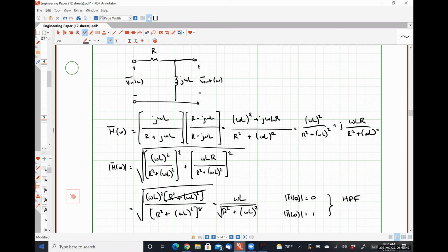But then you also get into problems called the skin effect and all that kind of good stuff, where you have to be careful about the size of the conductors that you use, because at very high frequencies... so in a DC circuit, all of the current that passes through the conductor uniformly distributes through the cross-section of the conductor. So there is a uniform current density flowing through all parts of the wire. Well, as the frequency increases, you'll find that the current gets more and more concentrated towards the outside or the surface of the wire.